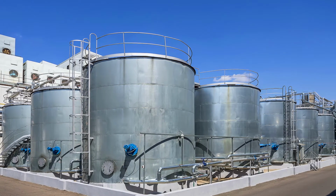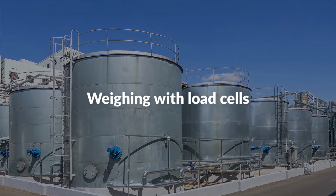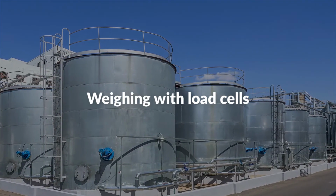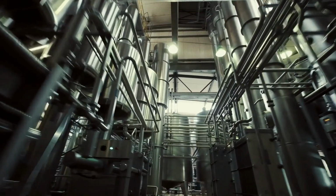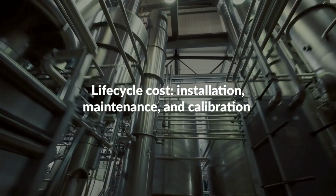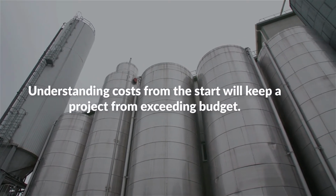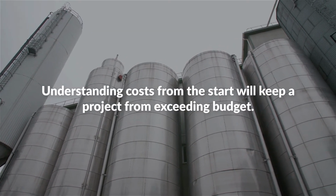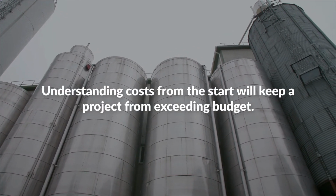There are other ways to measure level, such as by weighing the vessel and its contents with load cells. In most applications, any one of several different level technologies could be made to meet the requirements. Often, the deciding factor is the life cycle cost, which includes the costs of installation, maintenance, and calibration. Understanding all of the installation considerations at the start will keep a project from exceeding budget and help minimize headaches.